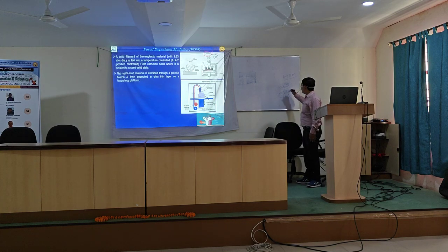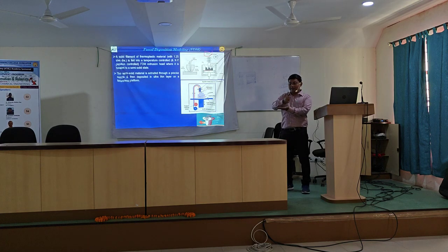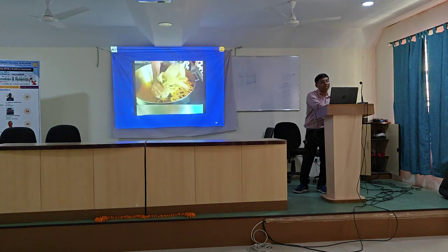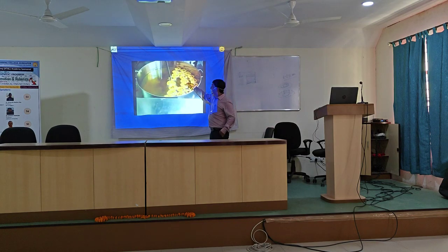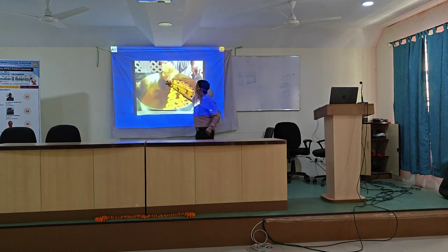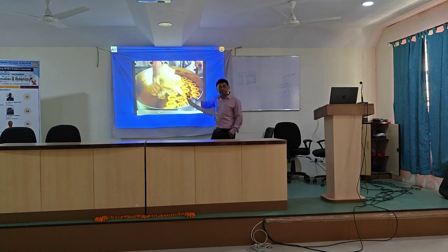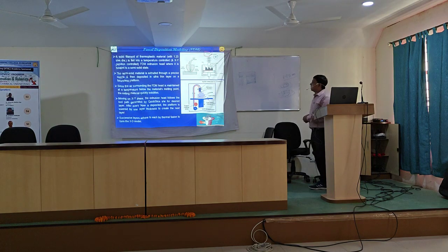How will it deposit the material? First it will deposit the outer layer, then the inner layer, and inside also it will deposit like this. Just like you take toothpaste, you open this one, and you just deposit the material. Outer boundary, inner boundary, and inside. So sometimes jokingly we call this similar to a jalebi making machine. Jalebi is also the same thing, though it is a 2D simple geometry, the process is similar. This is your nozzle, back pressure is created by hand, and the hand also has XY movement, and then at the tip there is a nozzle, and semi-solid material will deposit. The same thing happens in the case of an FDM machine. So it will deposit the material.